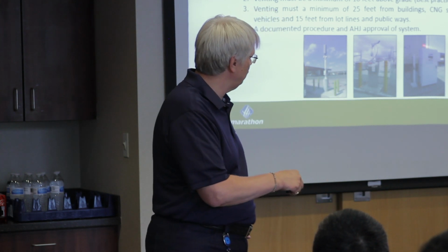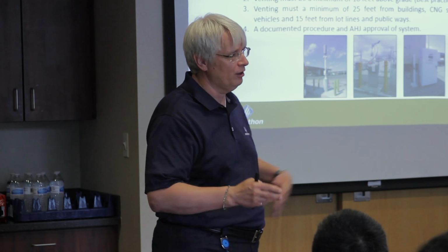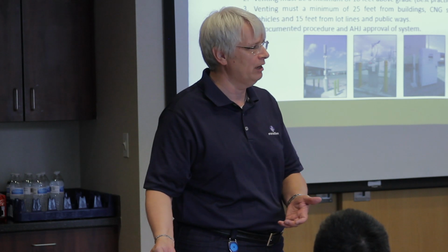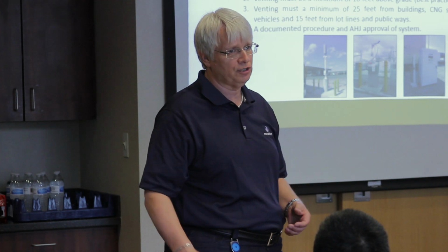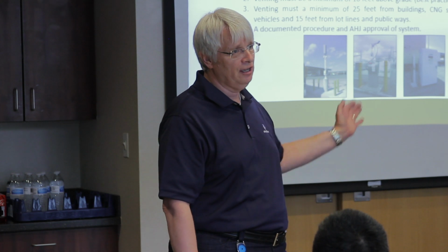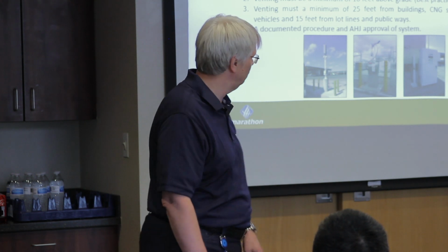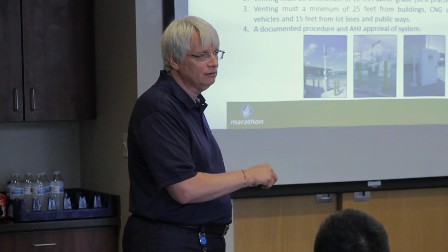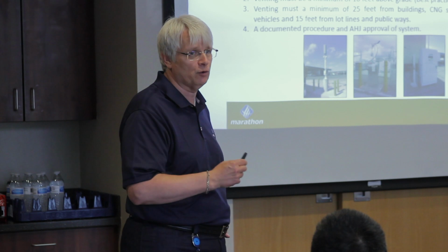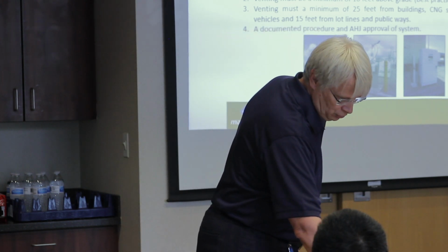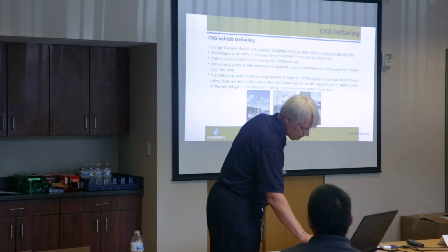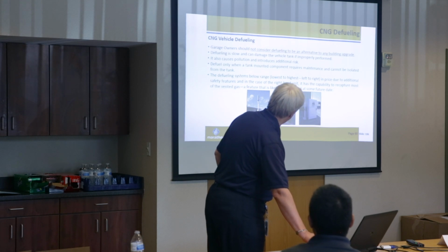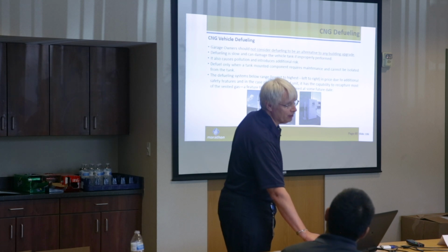And this defueling operation needs to be set up somewhere kind of out of the way, offline, because it takes probably a minimum of 2 hours, maybe 4 hours to defuel these tanks. And you don't want to do it too quickly, as I said, because you can actually damage the tanks. So, okay, that gives you an idea. This one is actually where we're kind of pushing our customers at this point, because we think they're going to get forced there anyway. So that was CNG. Pretty much covered this, I think. Again, I said that before, don't consider this to be an alternative to building upgrades.